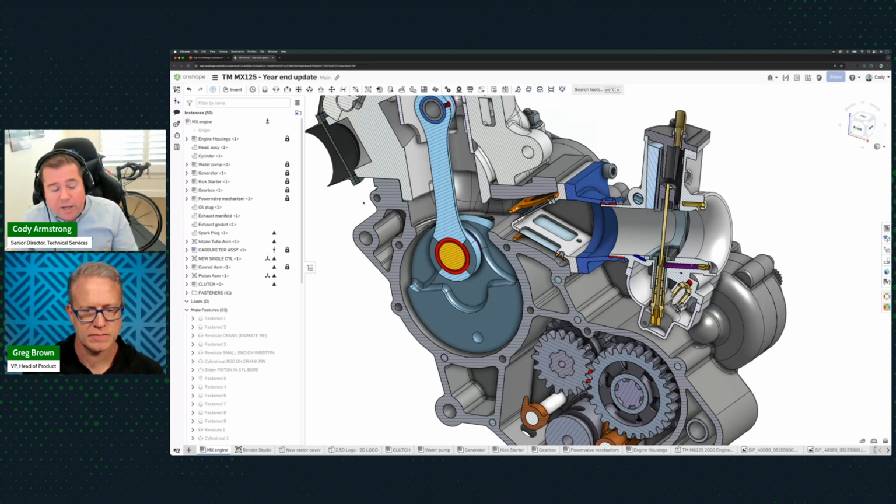And so it's easy for me, and what we find in most users is they really just want to be able to reflect the important positions of a subassembly in the top level. They don't necessarily need free motion, or the ability to grab and drag. It's just, I want to capture certain positions in that top level. This allows you to accomplish that. It allows you to quickly say, move this into the named position that I created in the subassembly.